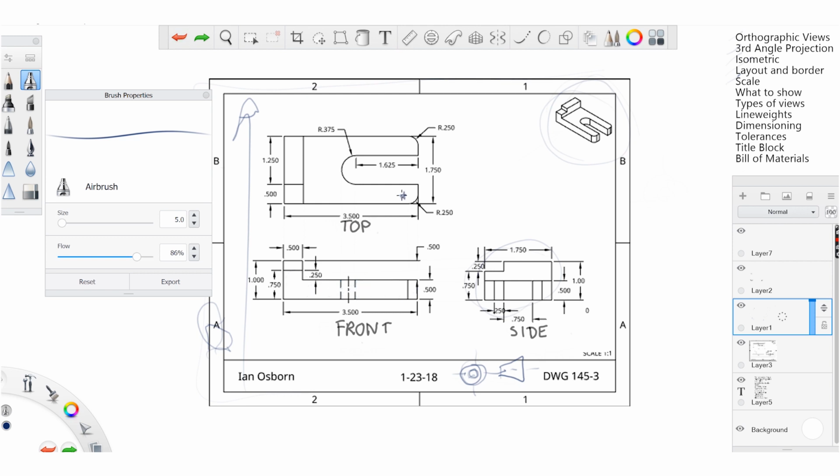You may also have a small detail here, which is maybe just a surface piece, and you would then have a little thing like this labeled A, and that would be a detail view, where you would then have a view here showing it much bigger and clearer, and it would be labelled Detail A.